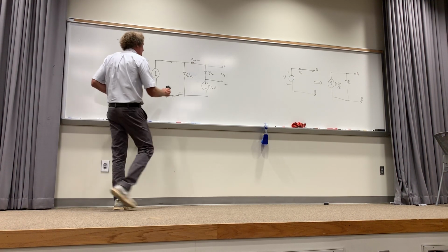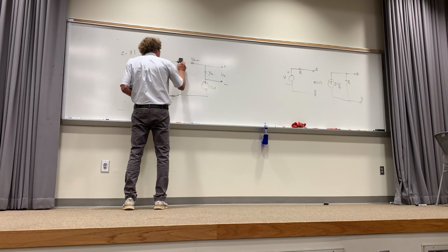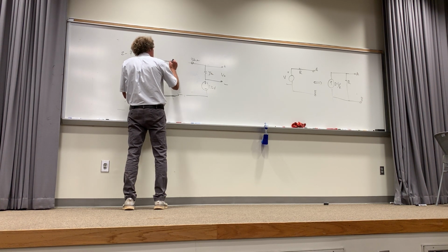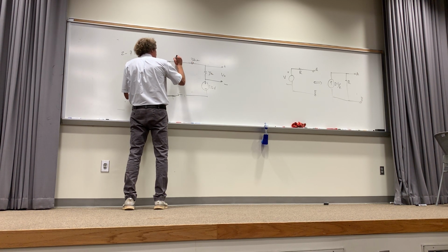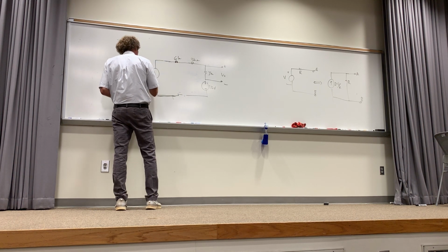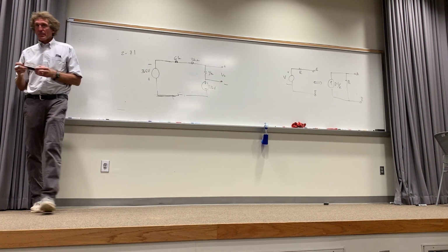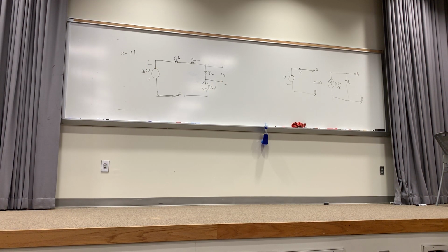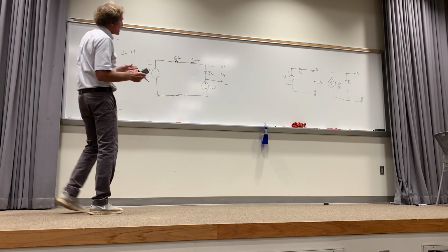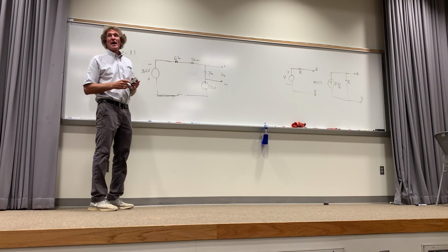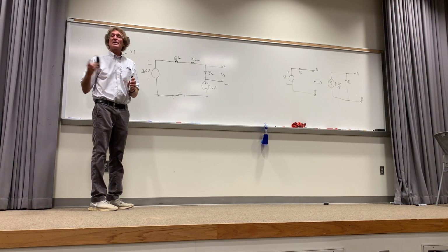So now, I go ahead and I get rid of this. I'm going to put my 6K right here. And now, I have plus to minus 36 volts here. Follow me? I just did a source transform with the current and the resistance. Now you by this time see what I'm up to, and most of you are very smart. I combine these two and I get 9. You agree? I'm speaking the truth.